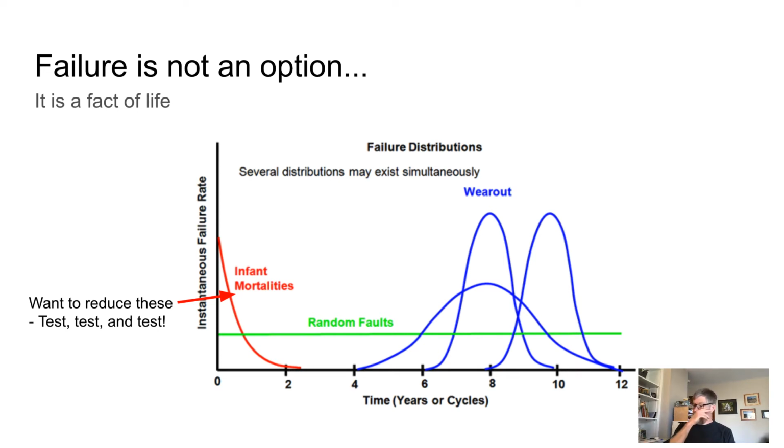This is like putting your Arduino in backwards. That is an infant mortality: you turn it on and nothing works. It's dead immediately. And so you want to figure out how you can mitigate against these infant mortalities. Like I said, testing, and testing. I have to say that the answer to all of these is testing.